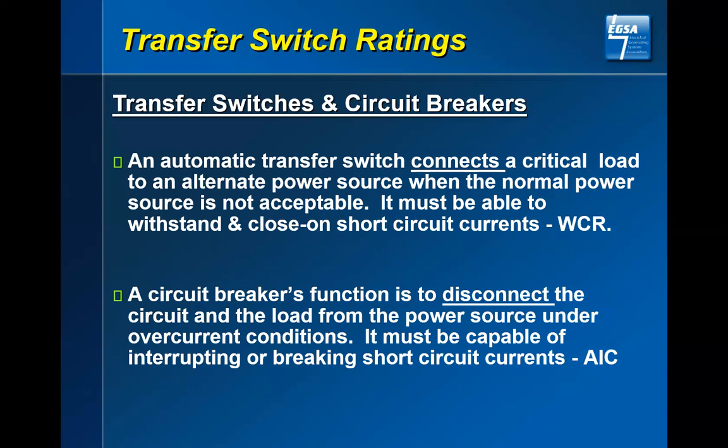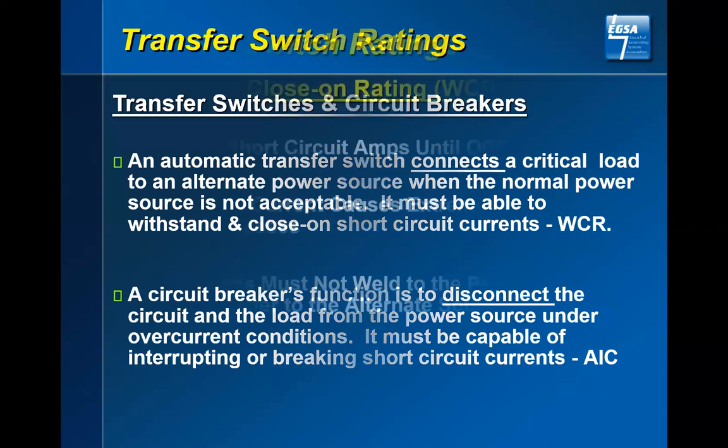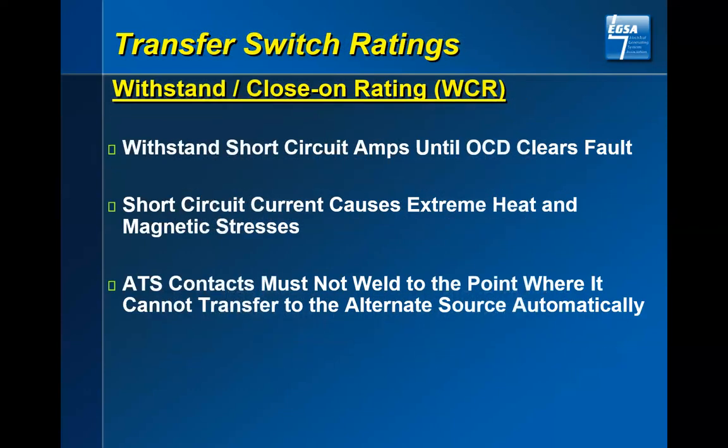Why do I bring that up? Why do I want to have to give you oversized transfer switches for a condition that can never happen? I may have to give you an 800 amp to 1,000 amp switch to do a 100 amp assignment because you have not given me a due diligence, a good number of what you can really have to withstand. Withstand and close on, again, we're talking about the overcurrent device.